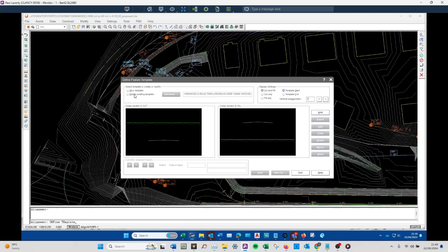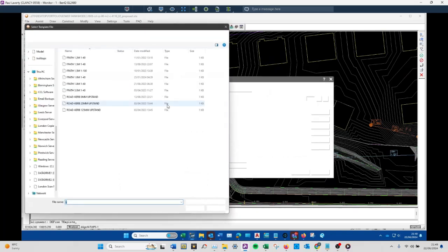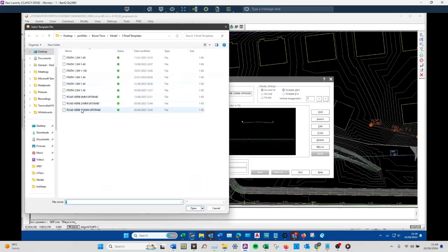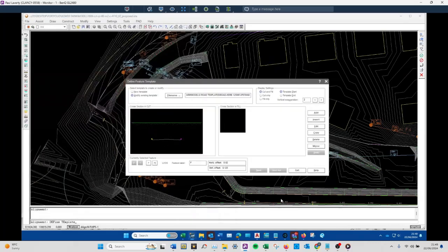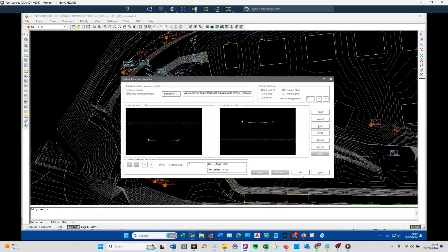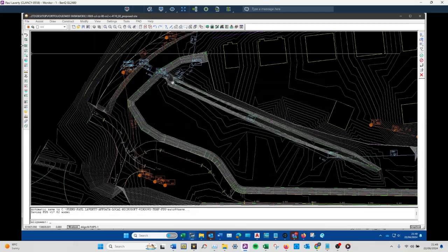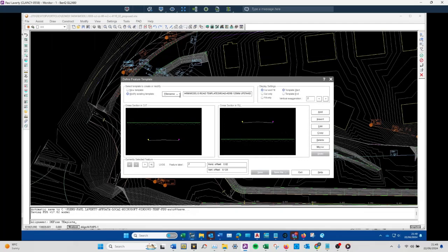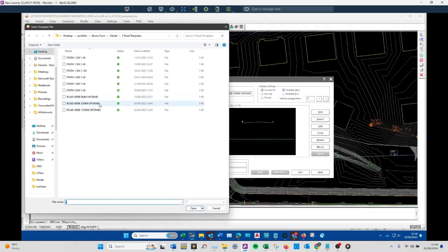So the good thing about PDS is you have these templates and you say, here's my road, I want to add a 25 mil curb. Bang, you select that, you go import template, choose a 25 mil curb, you hit your road carriageway on the left, on your right, bam, you have a vertical 25 mil upstand curb. And if that road dropped 200 mil, the curbs would drop as well.